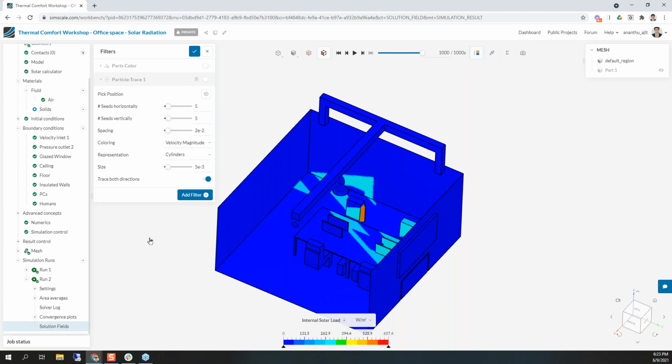And as we also saw, a more accurate calculation of MRT is then a next step that we'll take, and also, fundamentally in the end, coupling the structure and the fluid in one go, having a proper CHT analysis together with the solar load and surface-to-surface radiation. As we see currently, we're still analyzing only the fluid volume, and once we have the structure integrated, you can directly put in the materials of the solids, such as the chairs, and don't need to set a boundary condition for those.